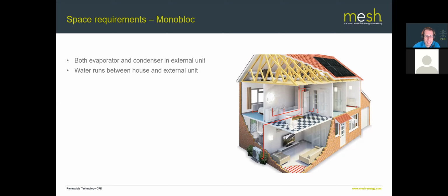And the second thing is that because there's no refrigerant lines being run, that entire refrigeration cycle can be hermetically sealed in the factory, and that means you don't have to have F-gas qualifications to install this type of heat pump. So a good plumber who's been properly trained should be able to set this up and install it without having specialist qualifications.